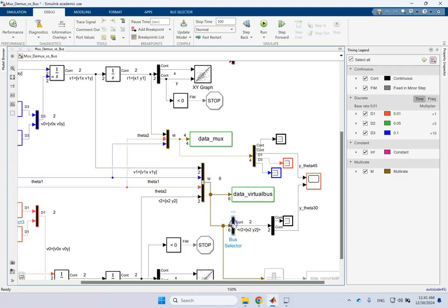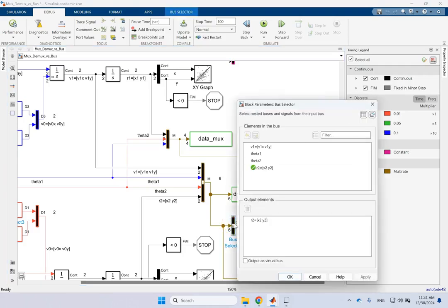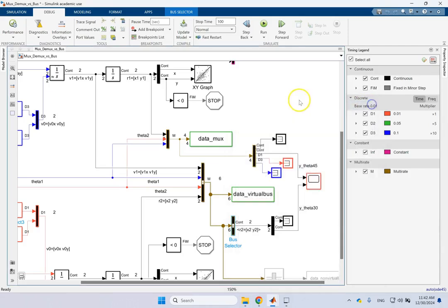Look here, if I go back, it shows me which entities, which physical quantities are available in the signal with the name, and then I can right click on them and simply add them to the output. So I get to pick exactly instead of just tracing. And that is way more powerful for organizing stuff. Okay? So you see the power of bus.